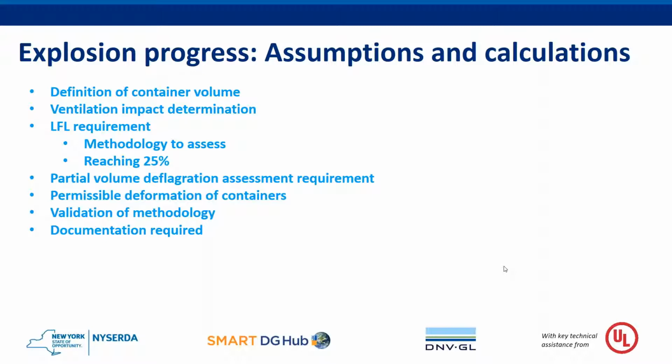If we're looking at an indoor installation, so a building, the term deformation is not really applicable, and it is required that there's no negative structural impact from an explosion. For the validation of a methodology, it's recognized that all methodologies are based on assumptions and past work, and that batteries being a relatively novel technology, and especially explosion analysis around them being relatively novel, those assumptions are not necessarily baked into all of the standards and methodologies for doing explosion calculations.